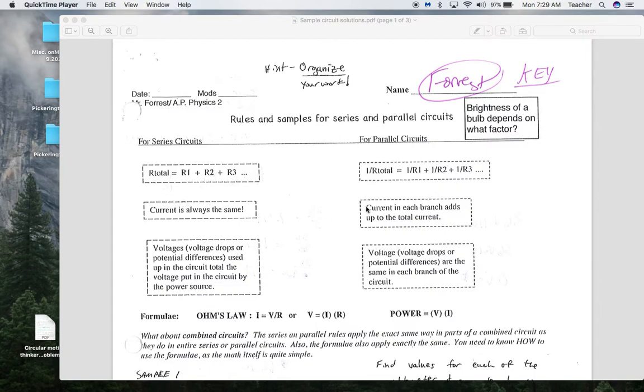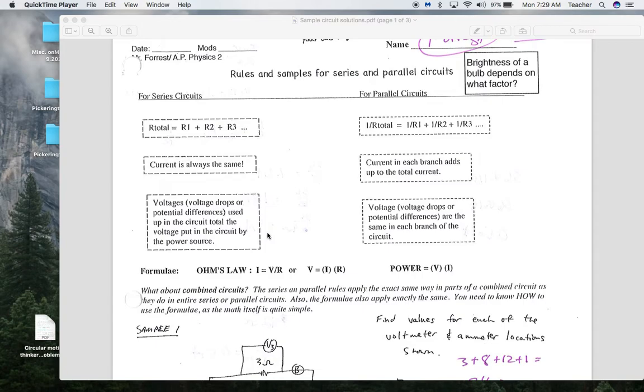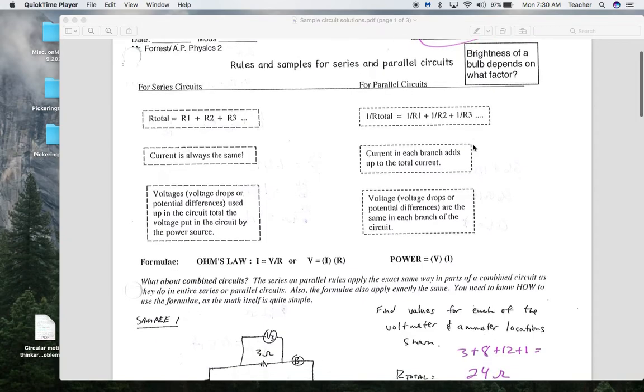So for parallel circuits, every time you add a branch, the resistance goes down, unlike for series circuits, where every time you add a resistor in series, the resistance goes up. Why does the resistance go down when you add a new branch with a resistor in it? It's because we have more paths for the electrons to flow. If you have more paths to flow, more electricity will flow. If you haven't affected the other branches at all when you add that extra path, then you simply add the amount of current going through the new path to the amount of current going through the other paths to find the total. So if you're adding more current, you're effectively lowering resistance.